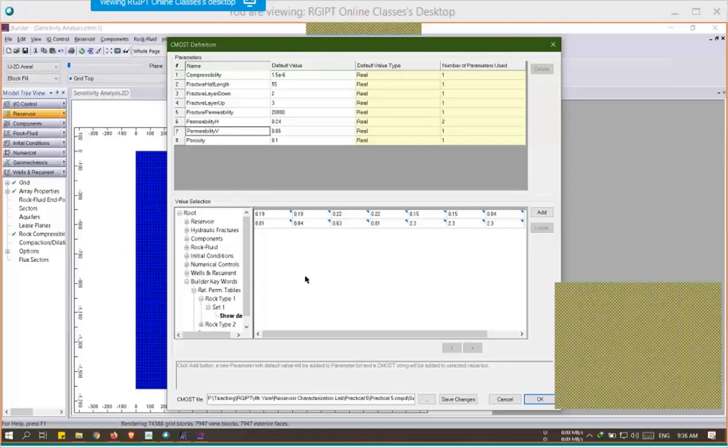So all those parameters were there, and to see the keyword, we can click on this, and it will show that this 0.19 value is for SW con, that is connate water saturation. This 0.19 again is for the critical water saturation. So if we do not know which value is for which, we can click on that and see which value is for which parameter.